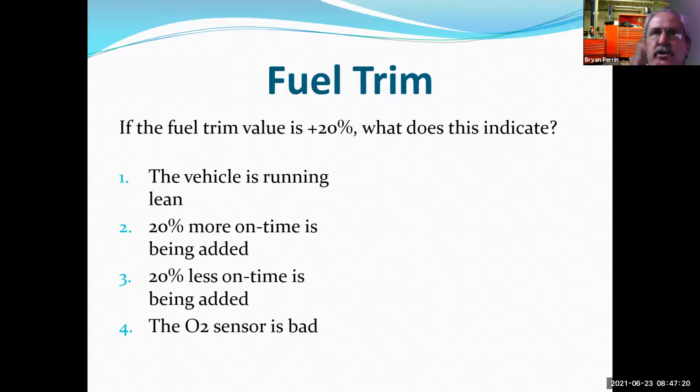It should still be in balance. So as long as you're in fuel control, you don't say the car's running lean when you're managing it. In that specific moment in time it is, but then it's correcting for it. Exactly. What it's saying is I'm having to open the injector up longer to compensate for what I perceive as a lean condition.